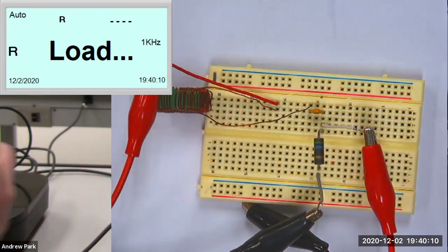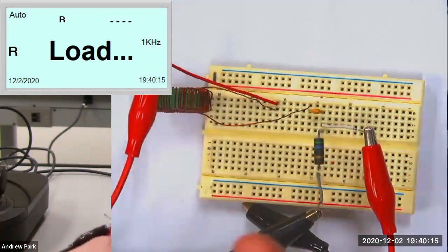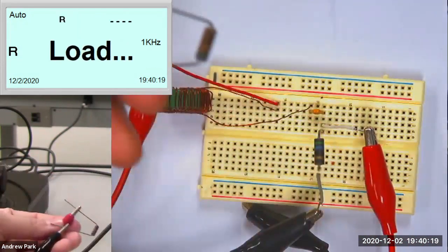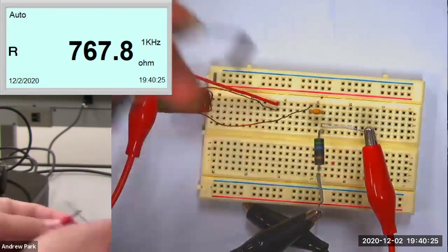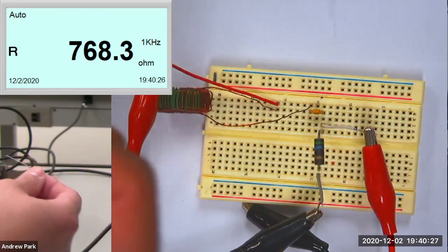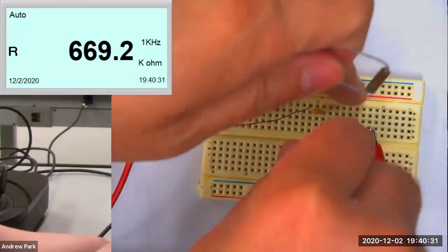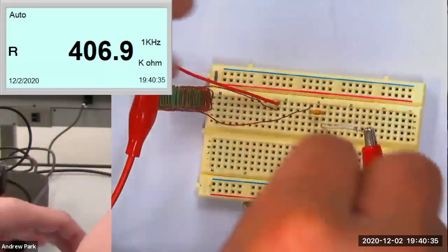Either way, I'm gonna measure it, so it doesn't actually matter what the box is labeled. It matters what the resistor is, and I'm gonna measure it so that I know what it is. Okay, 767, but out of a 750 box. So let me use that to replace the 50 ohm resistor.